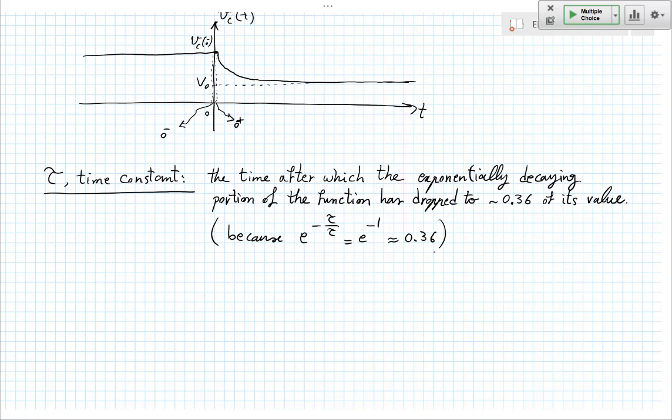I think you had this example in the lab where you looked at an RC circuit similar to this, where you saw that in one case your circuit had enough time for the capacitor to charge during each cycle, but then when you increased the value of the resistor by a factor of 10, your RC went up by a factor of 10, and the circuit didn't have the time for full charging and discharging. Did many of you see this in your lab? Yeah. So this is that effect. So this is the time constant.